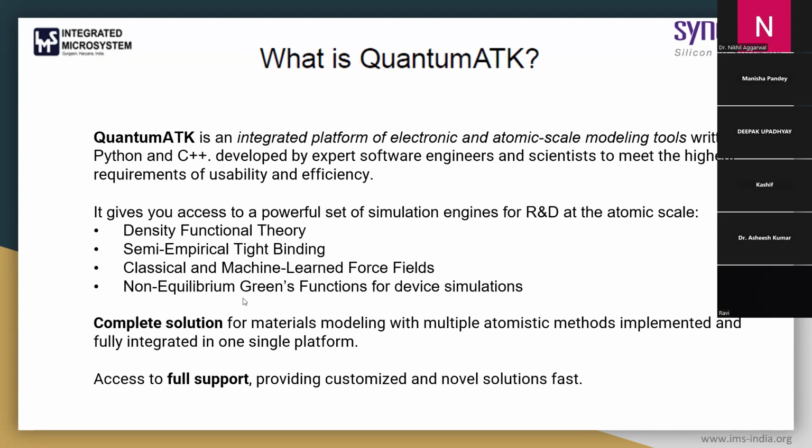And then we have non-equilibrium Green's function, which is for device simulation. This module is for nanoscale device and transport simulation. Using the non-equilibrium Green's function methodology, you can use either DFT LCAO or a semi-empirical model for describing the Hamiltonian matrix. Also, you can see here this term, machine learned force field.